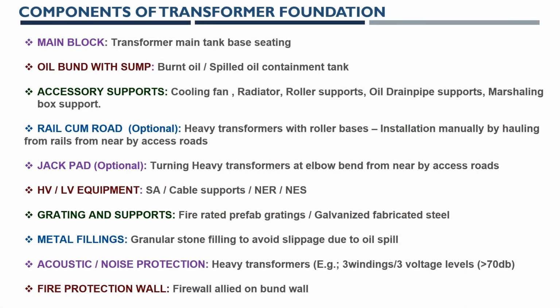So these are the various components. Of course, not all the components are applicable to every transformer foundation. There are certain components that are common to every transformer foundation, like the main block. This main block is where the transformer is going to sit. It will be like a combined pedestal or overall block holding the entire transformer base, or like transformer hauling beams or hauling wall. Totally we call that a main block.